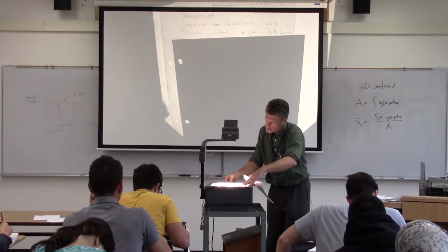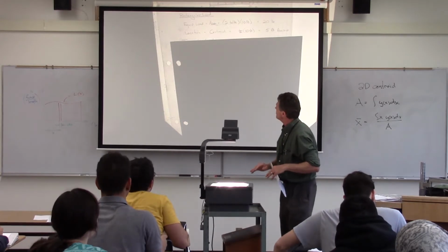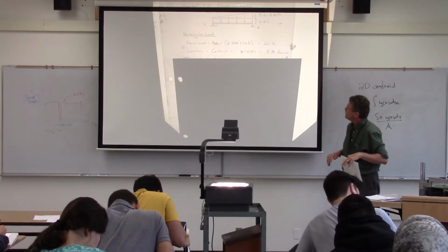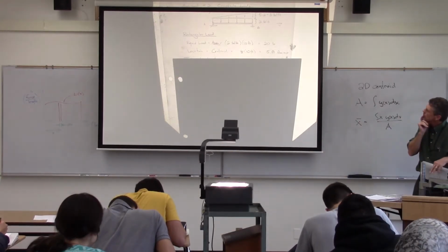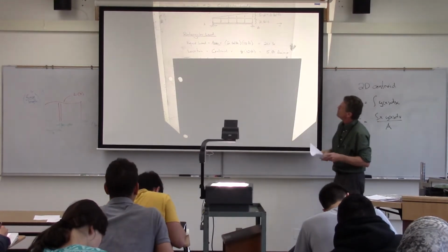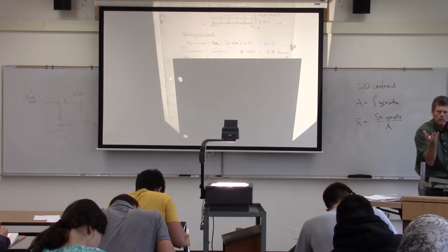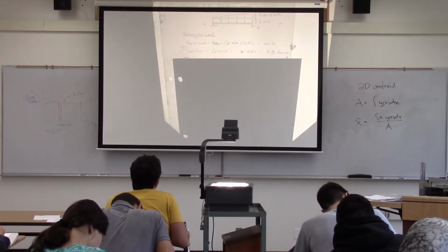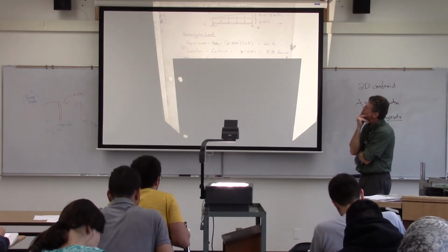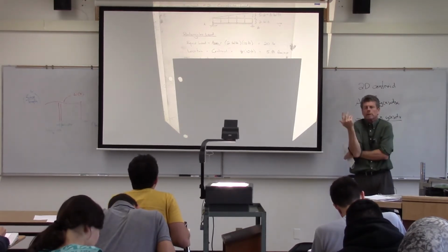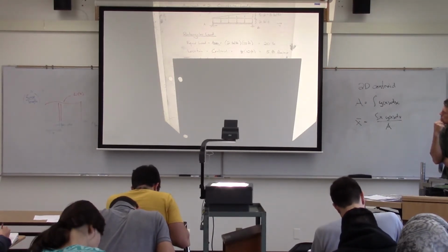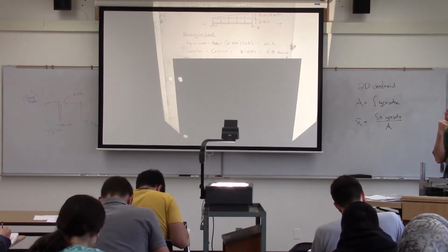And then what we're going to do is look at each of the pieces and get the information we have for those. The rectangular area there is pretty simple, 2 times 10. Notice it's in pounds per foot times foot, so we end up with an equivalent load. So that rectangular load is equivalent to 20 pounds. And then the location's even simpler because it's in the center of the rectangle, so it's just going to be 5 foot over from either end.